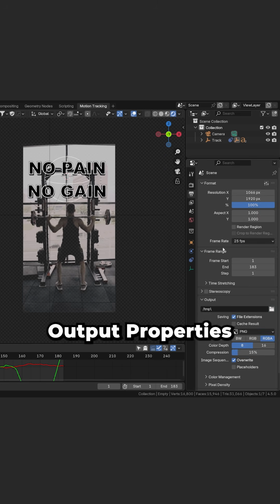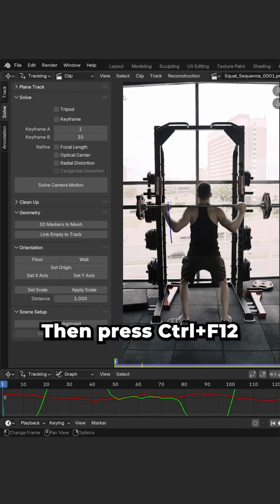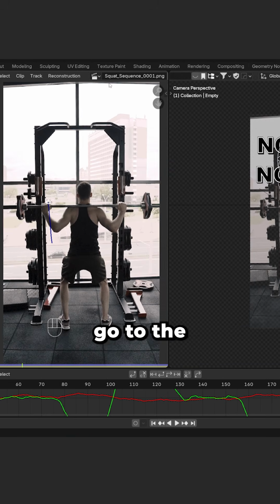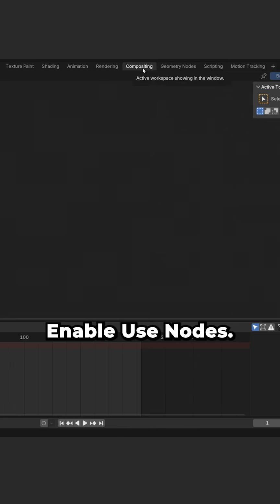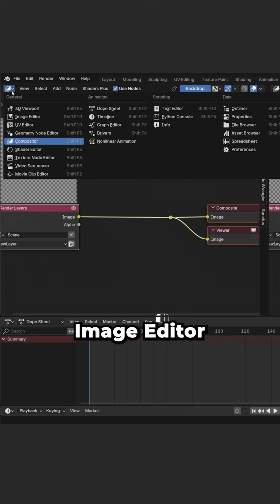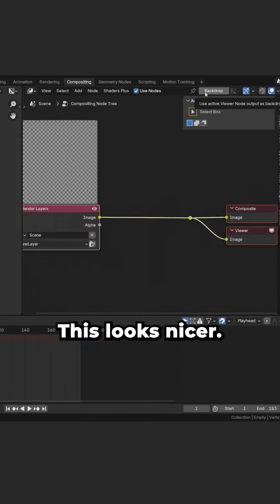Go to Output Properties and set an output folder for the animation. Then press Ctrl F12 to render it directly as a transparent image sequence. Or go to the Compositing workspace. Enable Use Nodes. Open up a new window, set it to the image editor and set the image to Viewer node. Then disable Backdrop. This looks nicer.